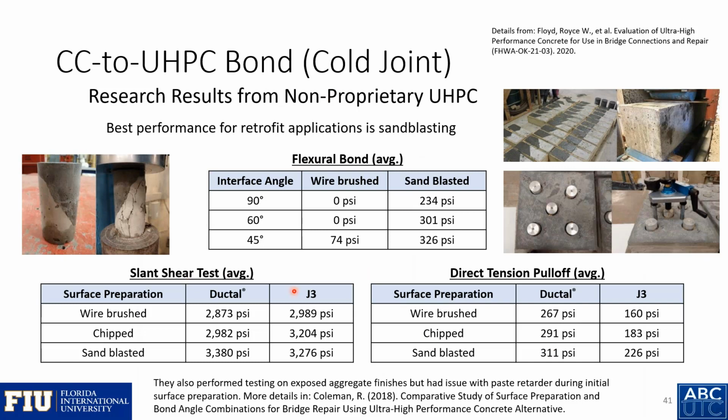As Dr. Floyd mentioned, they did some testing with non-proprietary UHPCs, and in general, they found that the best performance for retrofit applications was with sandblasting. And they looked at flexural bond, slant shear, and direct tension pull-off.